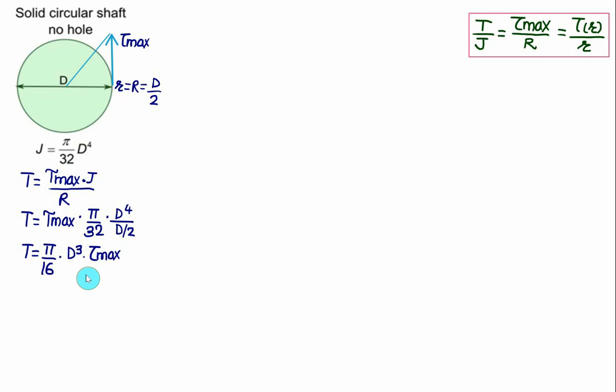And this maximum shear stress must be less than the allowable value of the shear stress. So we have tau max equal to the yield stress in shear divided by factor of safety. So you can confirm here factor of safety using the simple equation of a torque, which is given as pi by 16 into d cube multiplied by tau max.